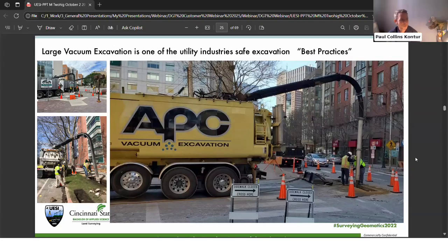So consider the size of your project, how many lanes you have, and whether you want to do some overlapping. Take the footprint of the antenna that you're using, and then consider the size of your job and the road speed. You can absolutely collect data at posted road speed, no problem at all, for pavement thicknesses.